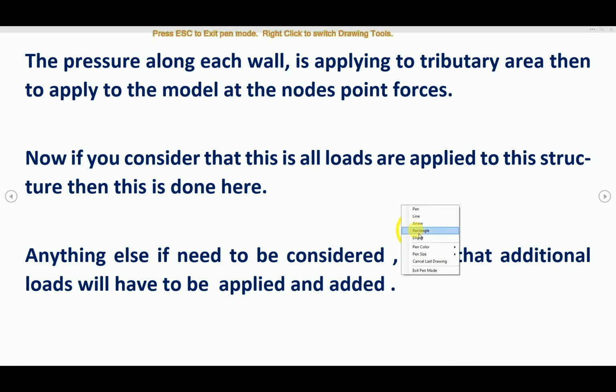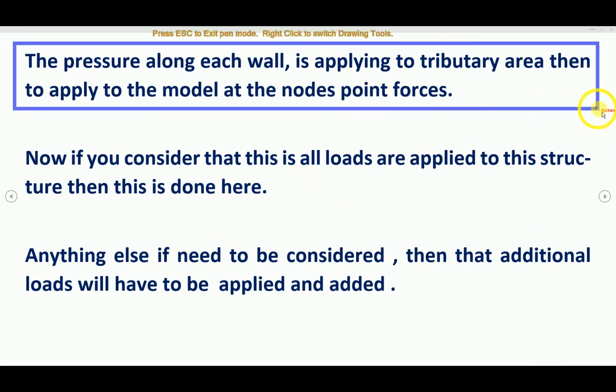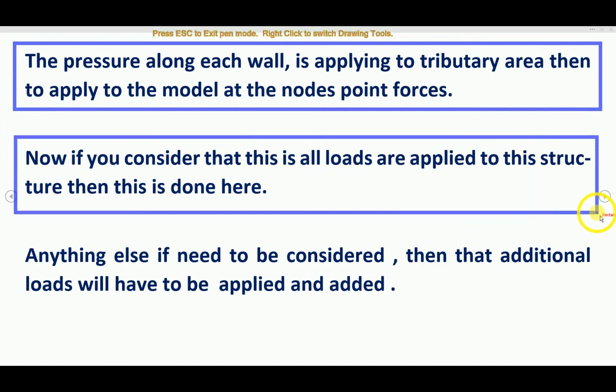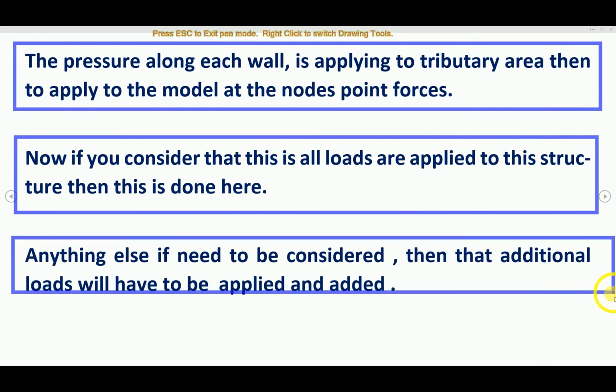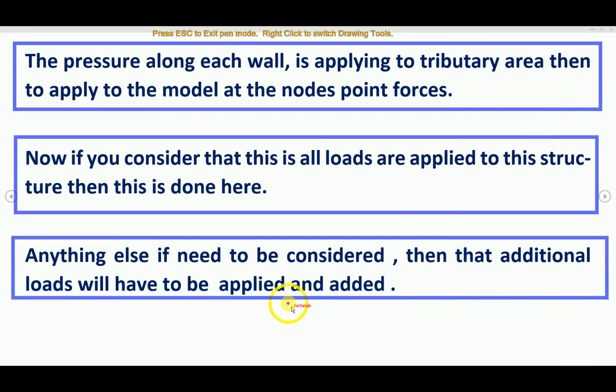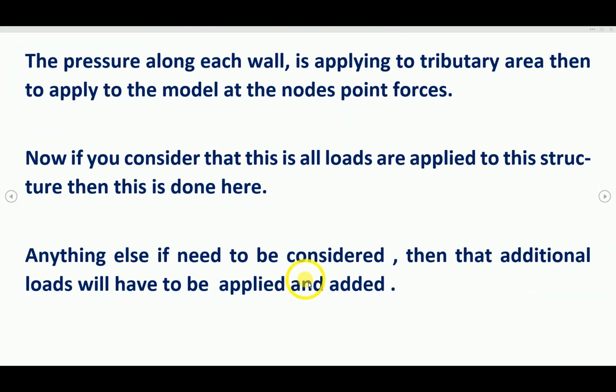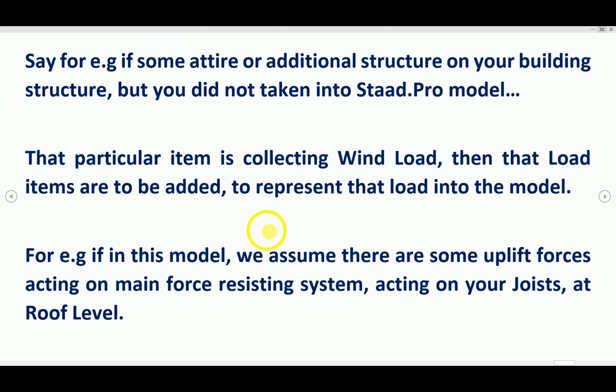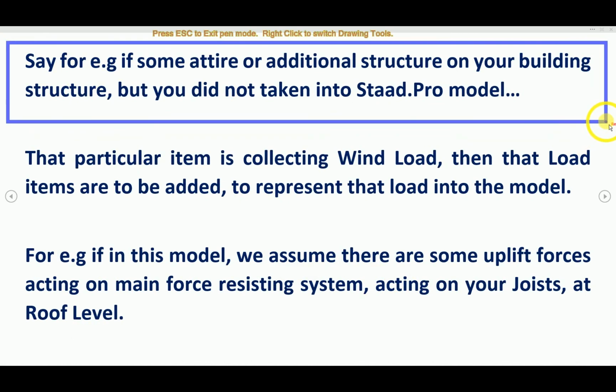But as an engineer, you will be responsible for determining which loads are to be applied and making sure they are applied appropriately. The pressure along each wall is applied to the tributary area, then applied to the model as nodal point forces. Now if you consider that all the loads are applied to this structure, then this is the sample of this model done.